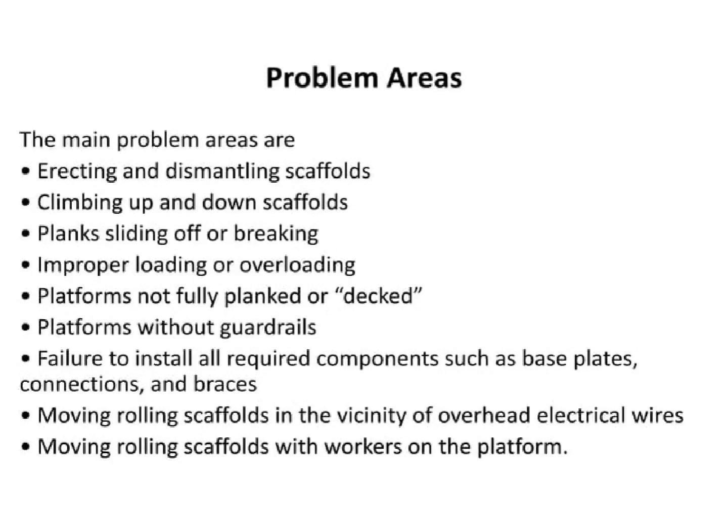Safety must be of utmost priority when working with scaffolds. Erecting and dismantling must be done safely, and caution must be taken when climbing up and down them. Scaffold planks should not slide or break, and should not be overloaded. Platforms should always be decked and guarded, all required components should be installed securely, and the safety of overhead electrical wires must be taken into consideration when moving rolling scaffolds. If any of these safety steps are not taken, it can lead to falls and injuries.